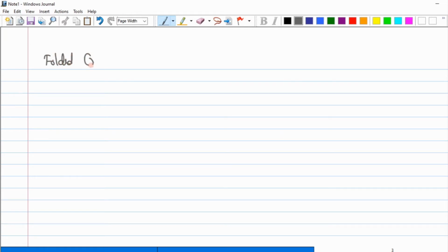So we call this structure the folded cascode, and there is a further refinement for this name. I'll just write it. What I've done here is take the drain resistance RD and retain M2 as my NMOS, but rather than connecting an NMOS towards the source of M2, I'm connecting a PMOS. Which terminal do I have to fix here?